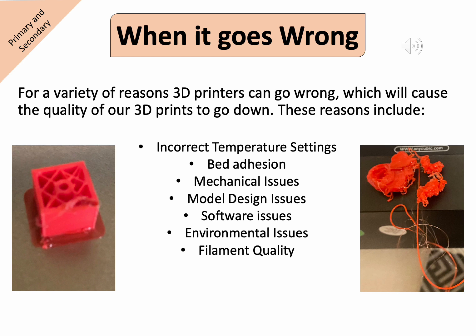We could also have model design issues. When we create the part in CAD, we can pretty much do anything in CAD, but that may not be creatable with a 3D print part. So this is something we have to bear in mind. We could also have software issues, so sometimes we're relying on the software to create the part. This might not always be right.